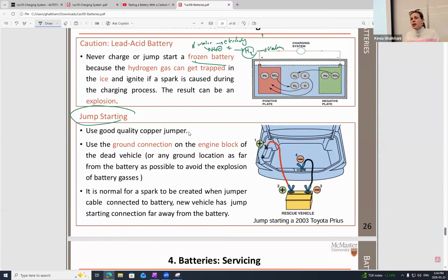Even here in Ontario, I see some people still do the same. They keep their battery connected to the outlet overnight to avoid such a situation and not have a dead or frozen battery in the morning. That's one solution, which, as I said, is dangerous. Because of that hydrogen, it may cause an explosion.